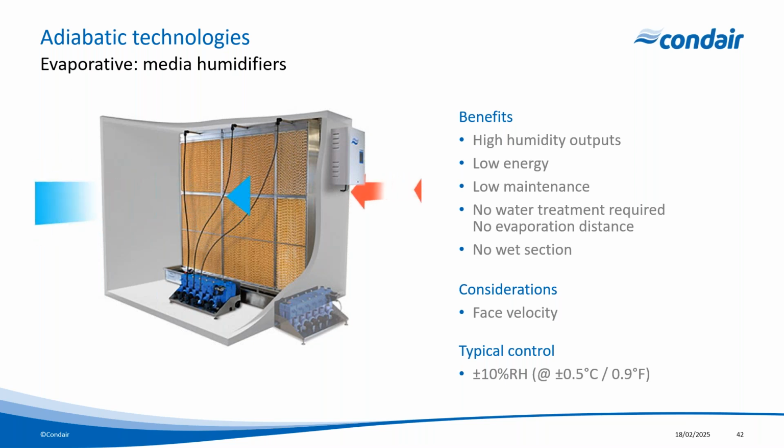Now, because the evaporation takes place within the depth of the pad, it comes down to the contact time between the air and the water. So if we have a really high velocity, we end up lowering the contact time between the air and the water, which results in a lower evaporation efficiency. The other potential issue with velocity is if it's too high, there's potentially a risk of that air pulling water off of the media, forming droplets that can make their way into the section downstream.